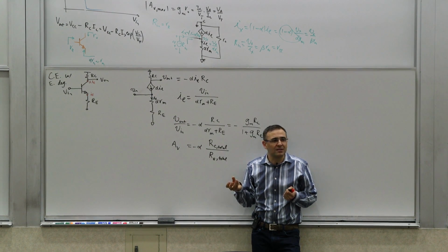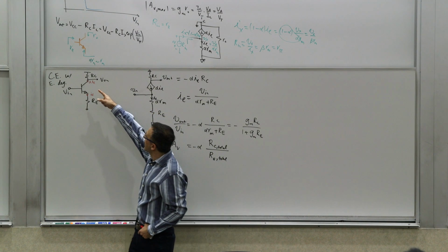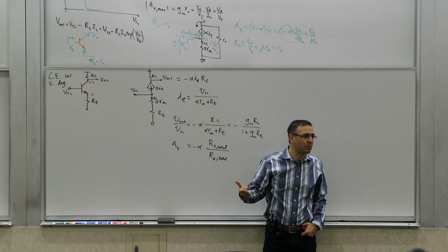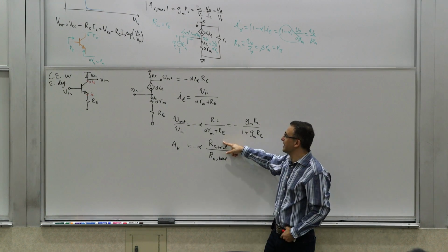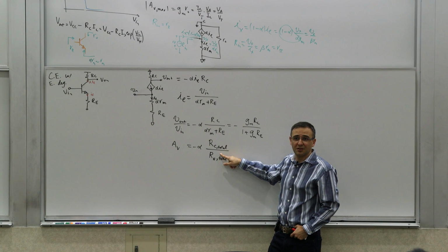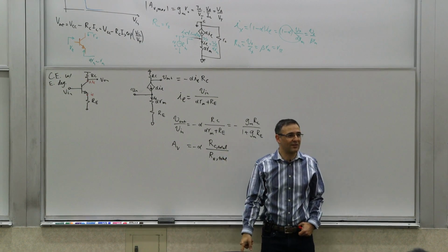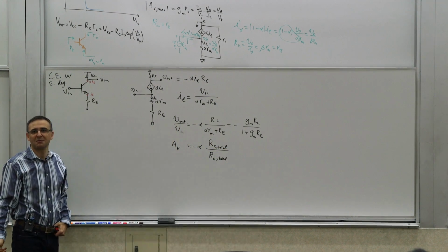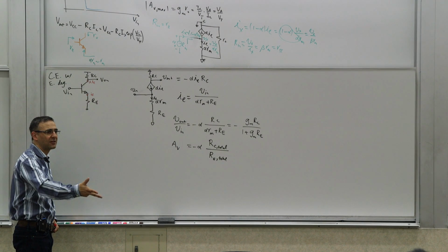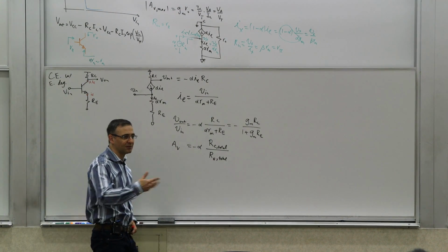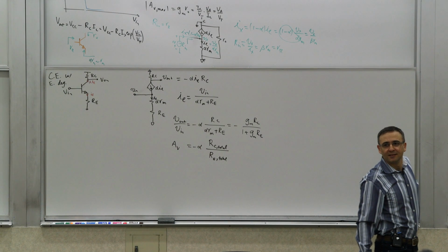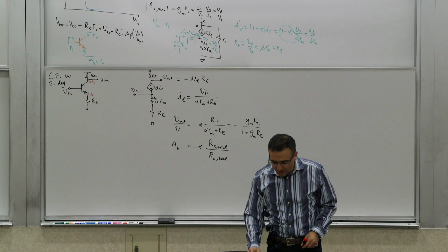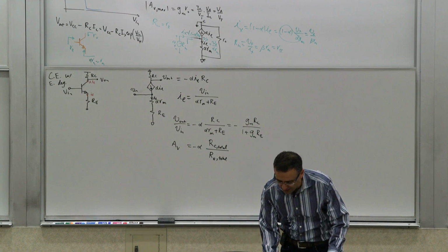As long as you have a device where these two currents are substantially the same, whatever device you pick, if you put a resistor in the collector, terminal 2, and a resistor in terminal 1, then the gain is the ratio of those two resistors. It doesn't matter if it's a MOSFET, a JFET, a vacuum tube, whatever. That's going to be the gain. Okay? So that's an important thing. It may appear simple, but it's important.